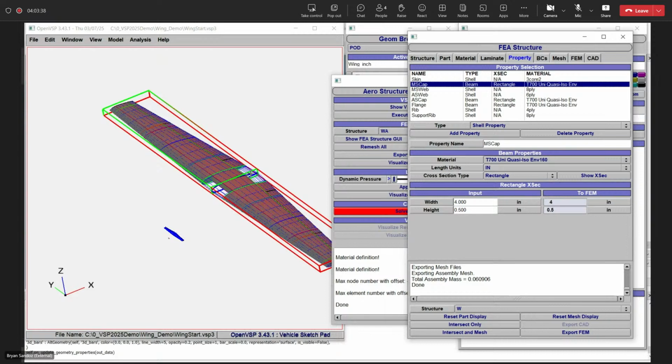You might have displacement requirements. You might want to thicken things up so that the wing doesn't displace as much. You can run modal analyses and stiffen things up due to modes being at prop blade pass frequencies or things like that. So that's kind of a start to end, in a nutshell.